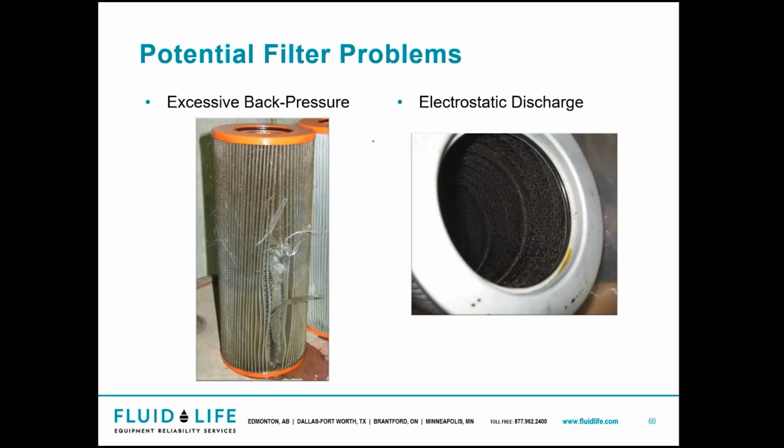And even when it comes to filters, like filter one shows blowout caused by high differential pressure. So what can happen is if you have too heavy of oil flowing too fast, boom, blow the filter out. So we want to make sure that we have the right filter flow rates for our oil and equipment specifications. As well, if our equipment's not properly grounded and we have that metal mesh on the filters, we could cause an electrostatic discharge if too dry of oil is flowing through that filter, and you're basically oxidizing your oil while you're trying to clean it.